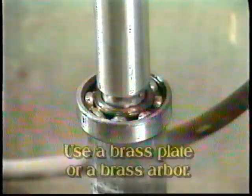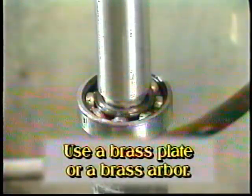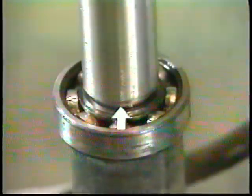Do not attempt to press with a wood block or any material that can compress unevenly or leave chips or splinters in the bearing. A brass plate or brass arbor is preferred, since brass is soft enough not to damage the surfaces of the bearing, but hard enough to push on the bearing accurately. Usually, there is a flange or shoulder that presses against the bearing to ensure that the bearing is positioned correctly.